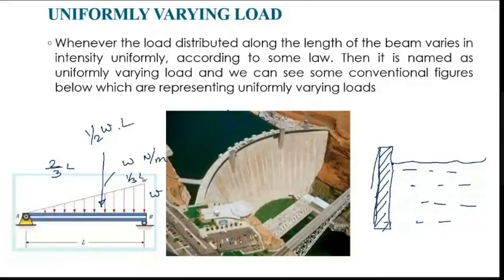The pressure is 0 at this location, but higher pressure at this location. Right? A uniformly varying load like this. Right, in your dam. So that's why your dam is not constructed like this actually. Your dam will be like this. Right, you can see.